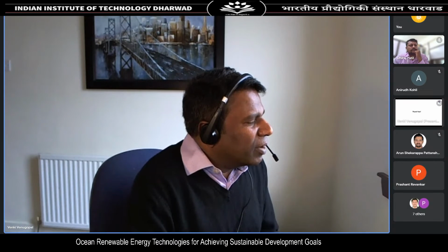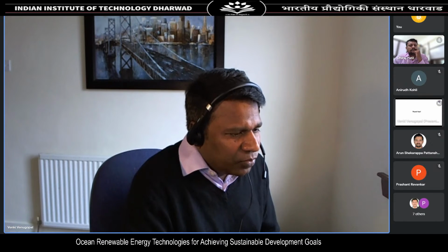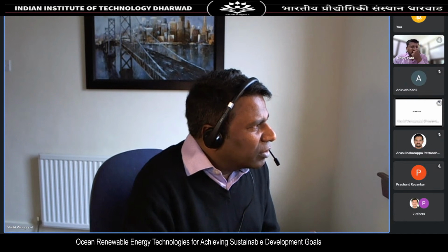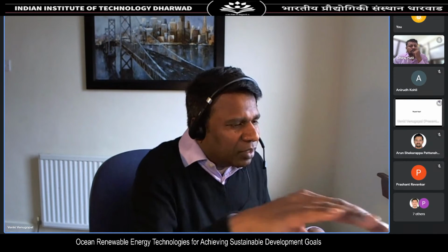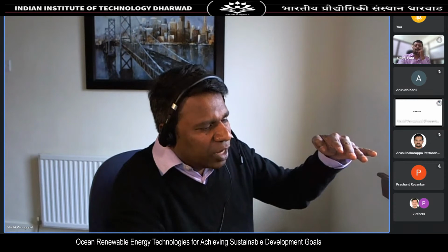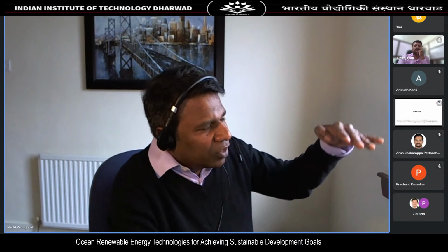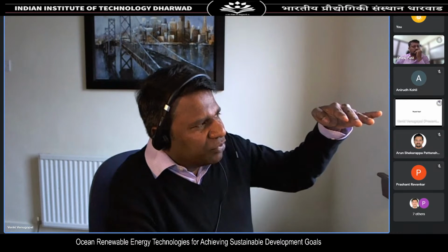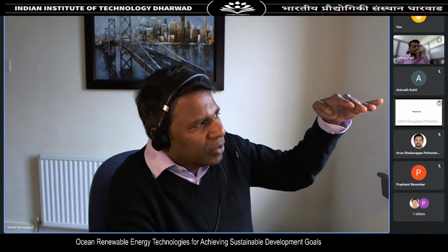That's very good for tropical countries like India. The NIOT, National Institute of Ocean Technology, they tried that. And also other locations in Chile and that kind of tropical, the countries close to the equator, they are very good for that. Because you would have very low temperature water. Say if you take a 500 meters water depth, you would have near zero temperature at the bottom and 25, 30 degrees at the top. So therefore the temperature variation could be very much used for the OTEC technology that you mentioned.